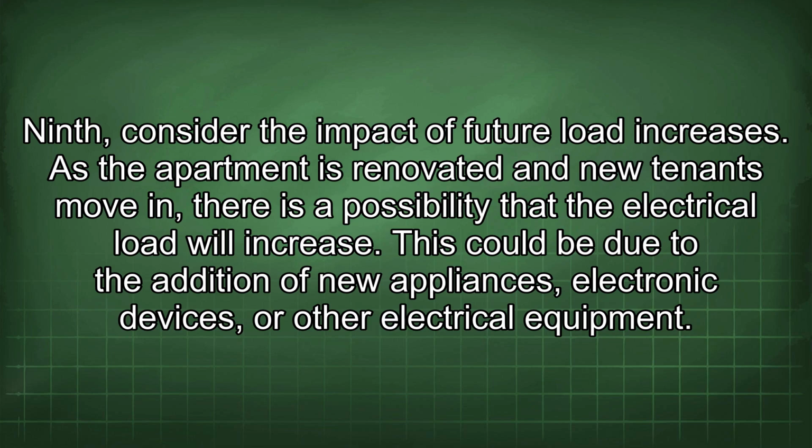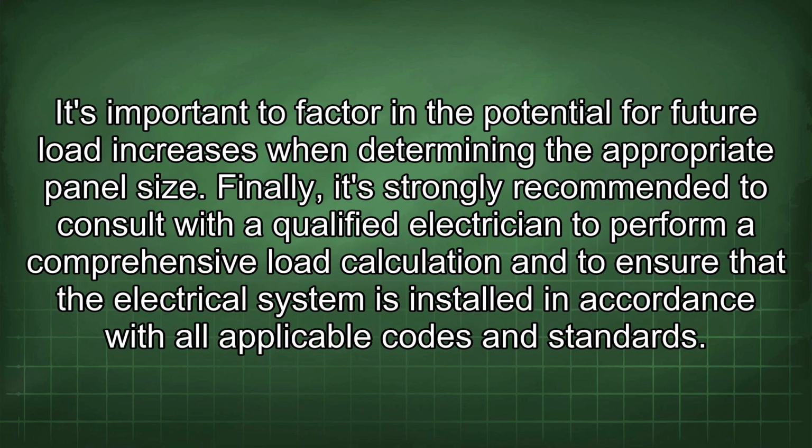Ninth, consider the impact of future load increases. As the apartment is renovated and new tenants move in, there is a possibility that the electrical load will increase. This could be due to the addition of new appliances, electronic devices, or other electrical equipment. It's important to factor in the potential for future load increases when determining the appropriate panel size.